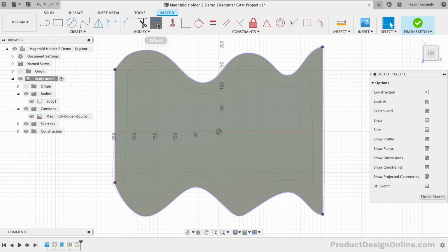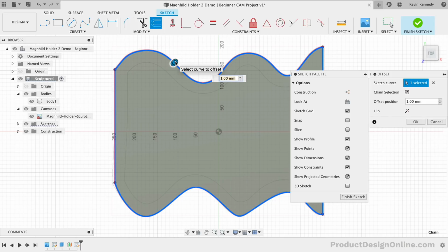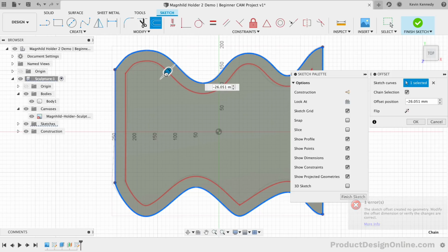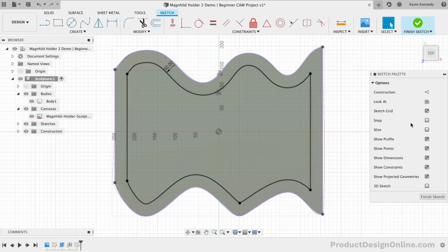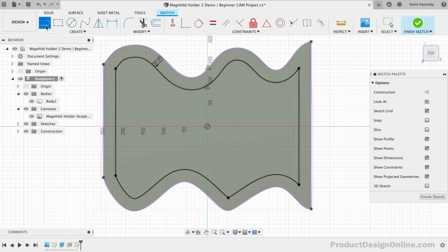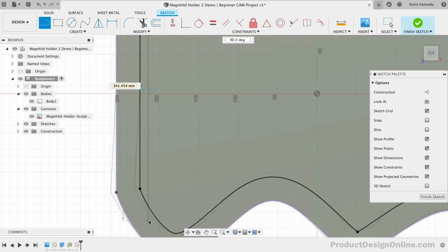We can now use the Offset tool, select the projected geometry, and we can drag the slider to position how far the geometry is offset. We can either eyeball the offset based on the reference image, or we can type out a specific distance, such as -30 millimeters. We're going to need a straight line for the pipe command to reference, so once again, we'll use the Line tool. This time, I'll draw the first line while making sure it extends past the highest point of each curve. You'll also see that a parallel constraint appears, making sure the line snaps in parallel to the line on the left.